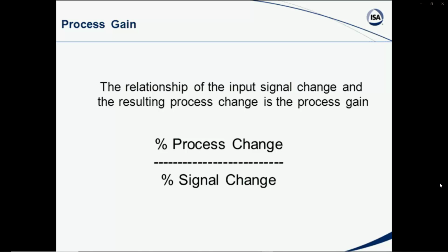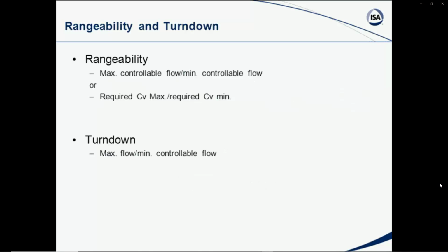So that's why the tuning, we talked about having the valve in its normal operating position, so that when you made a 10% change in the signal, you could see a process change that would really be representative of that particular process. So you need to always be aware of that.